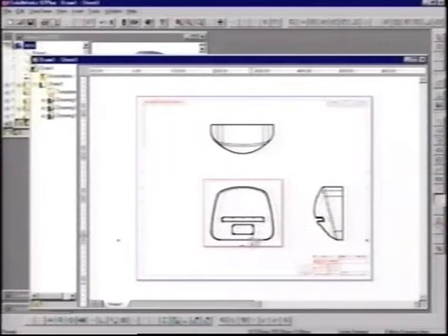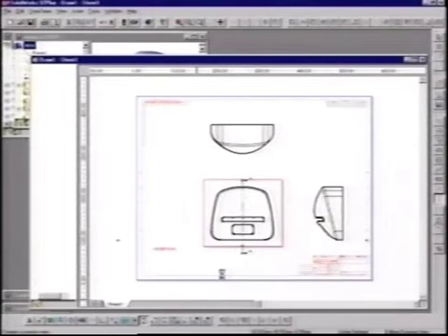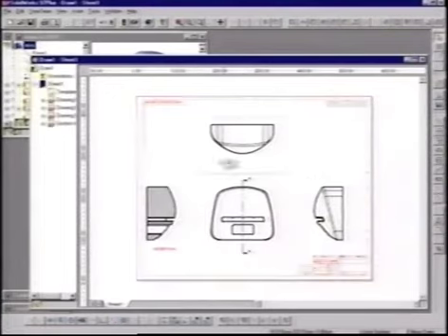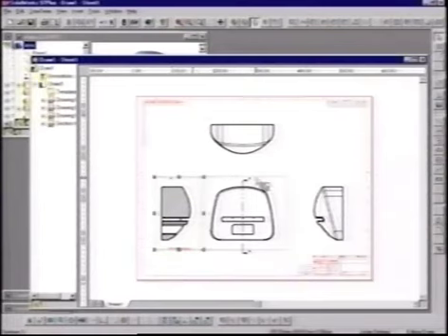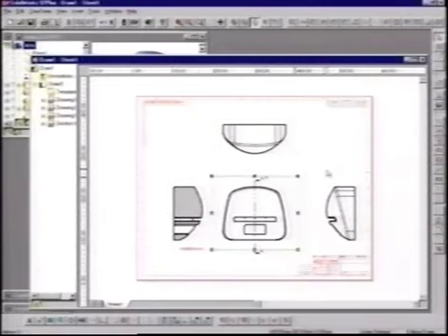The next thing we'd like to do is take a section right through the middle of the part. So Joe's going to sketch a section line right on the drawing view. Watch as the sketching tool helps him center that right on the part. When that's done, SOLIDWORKS automatically creates a section view for him because it understands everything about the geometry, even where